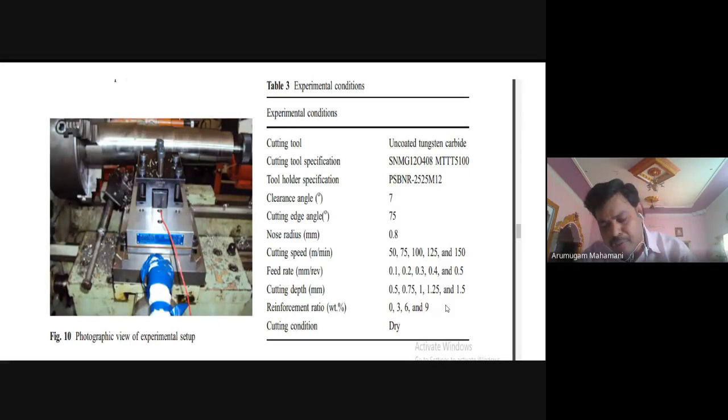While making the composite at 12%, we were using a cast iron die, with an upper half and a lower half connected together. At the joint between the upper and lower half, we added a mild steel pin. The high temperature melted the die connecting pin, and the molten metal came out, so we were unable to do it.